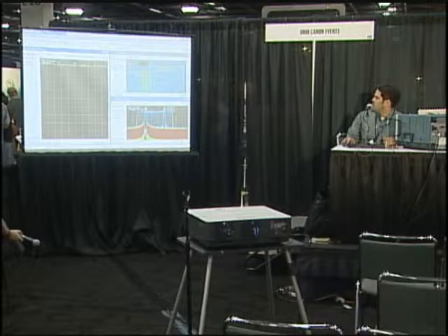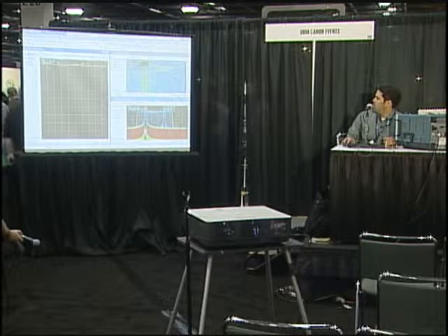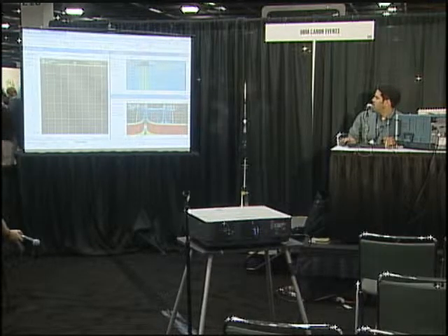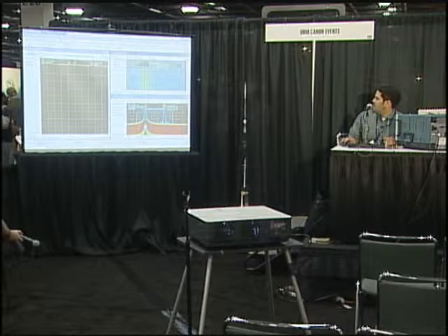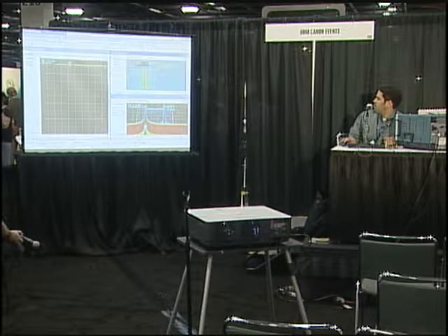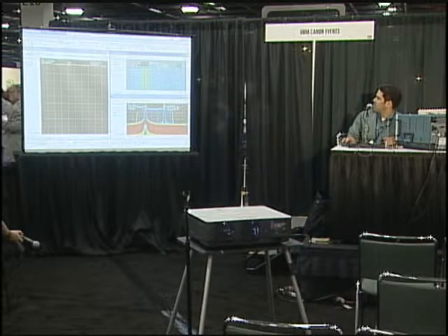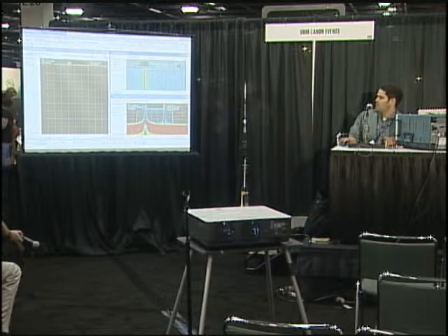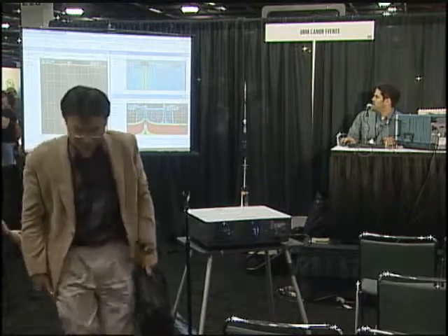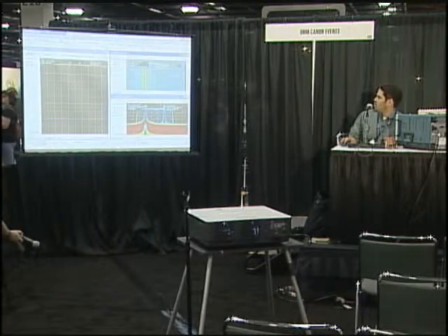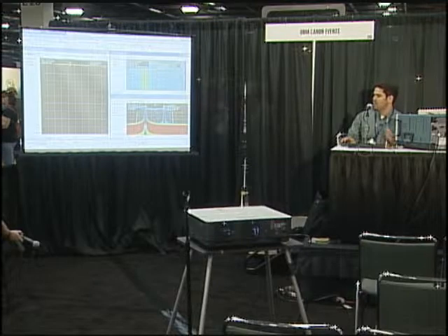And you can see when you move your cursor here on the time domain, see how it moves also on the spectrogram? We got a couple of cursors here, right? And they're both showing you the frequency, amplitude, and time of this one versus the same for the other marker over here. And like I said before, they're time correlated, so when you move it in one domain, it moves in the other domains as well.